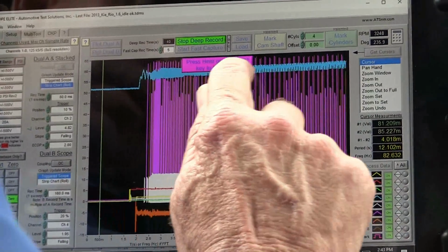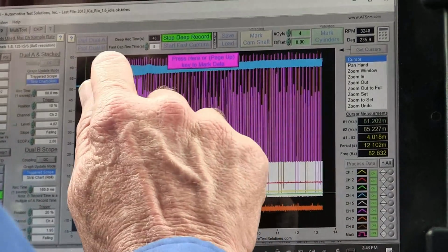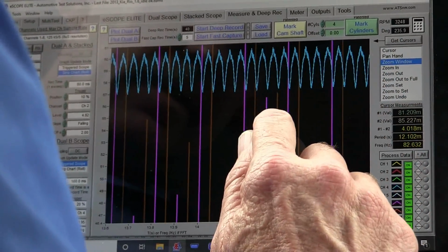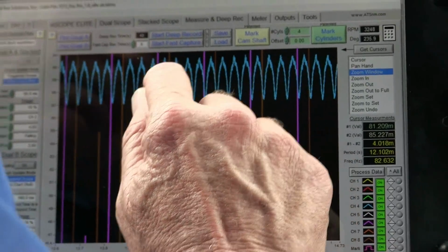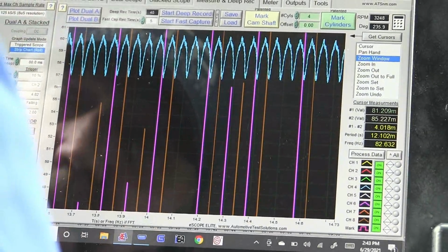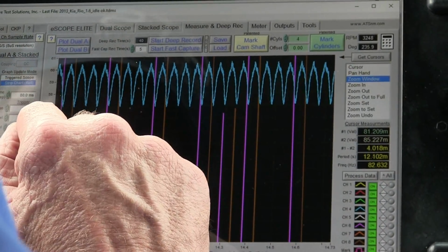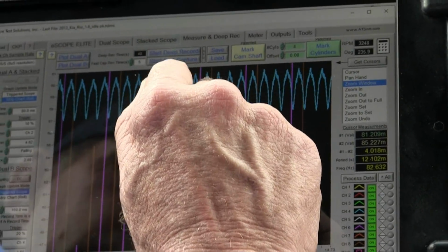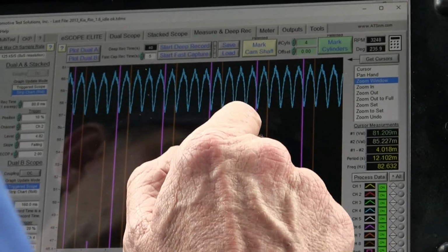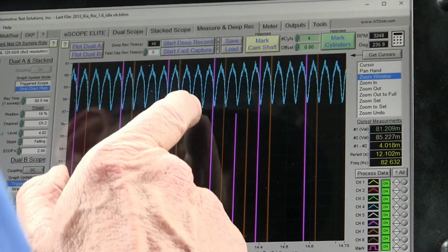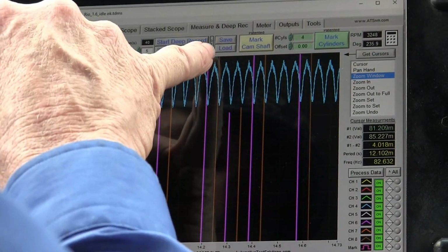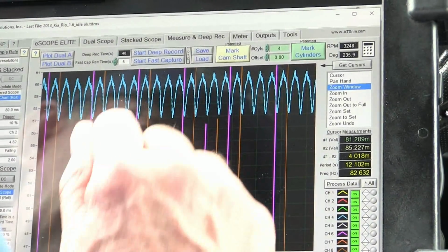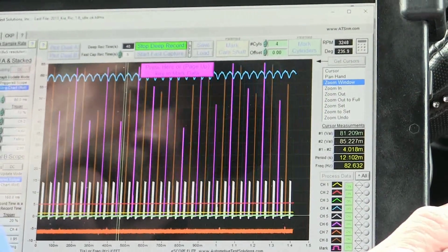Okay, so the blue is our pressure and this is the amp reading. Now something's going on with the blue. Look at how wide it is. So let's take a look at that. That's dropping pressure. I'm building pressure and dropping pressure. So basically I'm at about 60 pounds, but I'm dropping down to about 57 pounds. Every time the injector opens, it's dropping. You can see these injector strikes right here, that's the purple and the brown. Every time the injector opens, I drop that pressure. So I already have a problem with the feed side, the low feed side. So let's go ahead and drive the car and see what we've got.